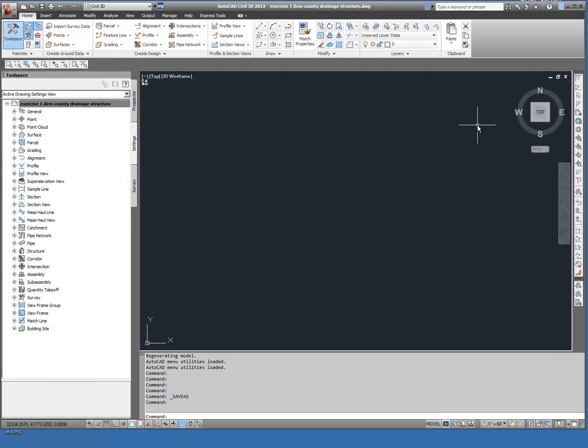Next we're going to connect to the photo. This aerial photo for Nicollet County was downloaded from the MinGeo website, and we're doing it this way because it allows for the photo to be part of your drawing. You can see the photo without having to have a live internet connection. So the photo was downloaded earlier, and it's in the format of a .sid or SID file. You will find it in your Exercise 1 folder. So to do that, we're going to type map connect.